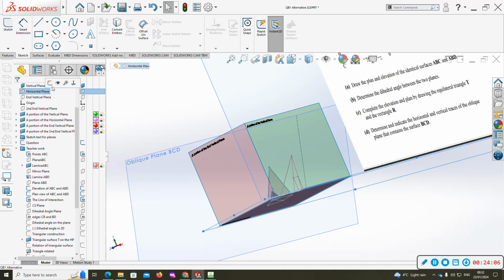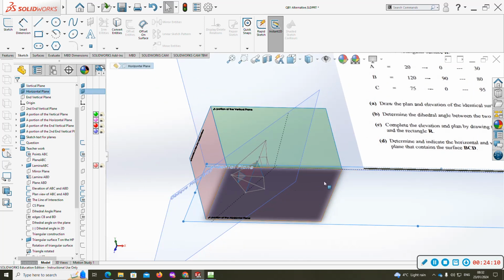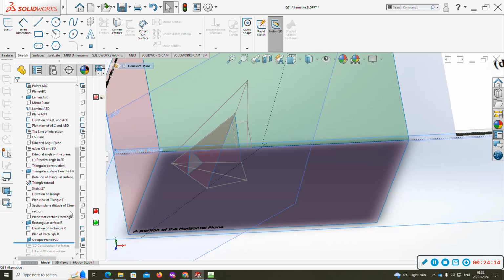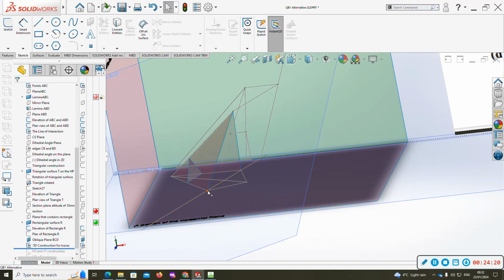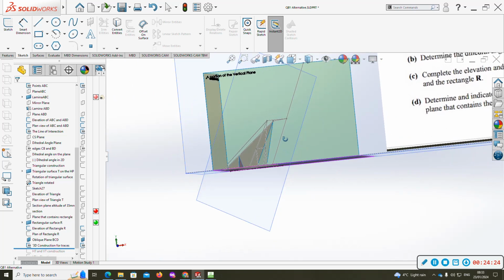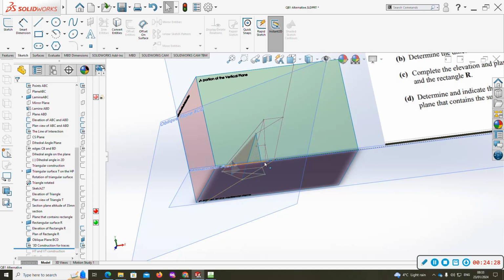And then when it intersects the horizontal plane, we get the HT. So that's what we're looking for, to find those lines of intersection. So how we're going to do it is we're going to realize that if points B and C are on the XY line elevation, they're on the HT in plan view. So I just need to join those two points together in plan view.